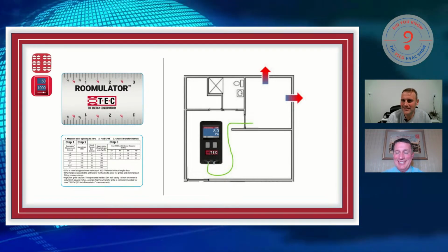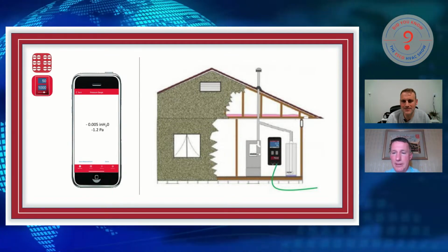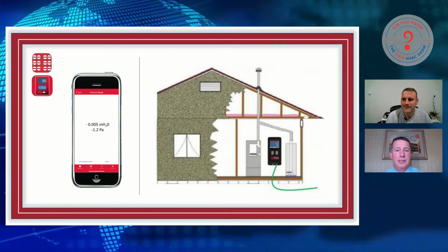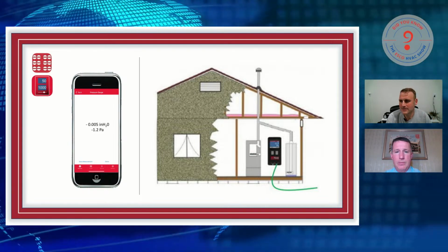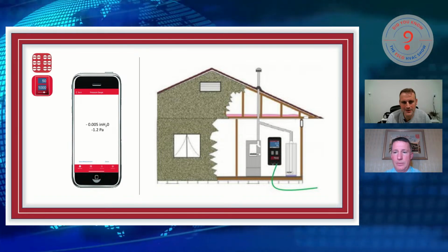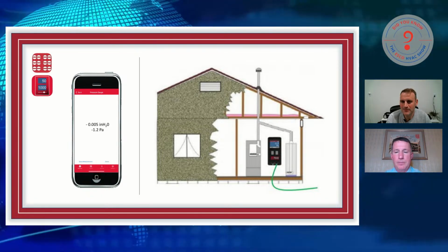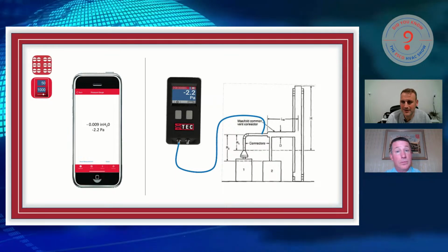Handy. All right, that's a little handy tool. I like that. But you need a micromanometer to get that measurement. A standard manometer is not going to get low enough. So just going to run through some of these. This one is combustion appliance zone testing, right, is your hot water heater backdrafting. You could check that with this manometer. If you want to see if your draft is drafting, you can do that.